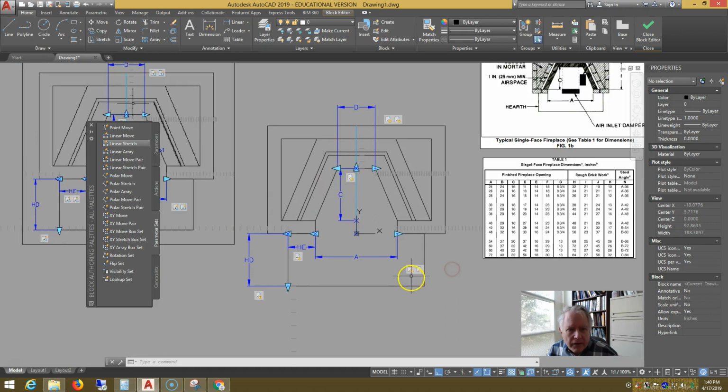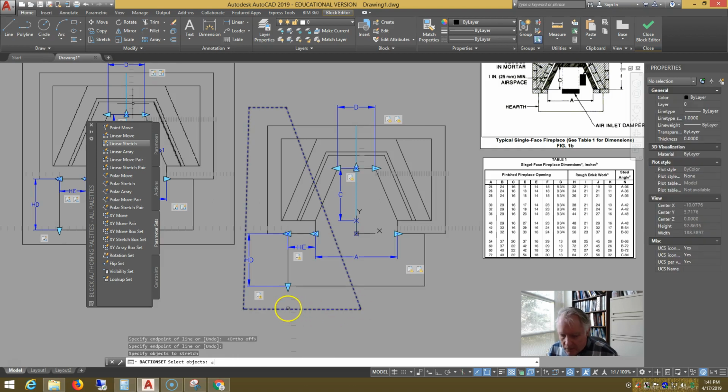Now, a little tricky here. Do you see when I hover over this, it gives me the left point of that parameter. So right-click, new selection set, CP for crossing polygon. Pick over here, go straight up to the top, go over a bit, and then turn ortho off, and go down here so it crisscrosses. And then crossing polygon, do the same thing.